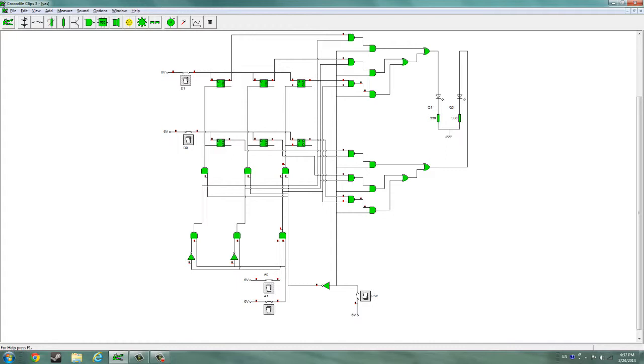Now, let's see how address leads work. There are 3 locations to save the data: location 1, 2, and 3. To save data in a specific location, you must represent 1, 2, and 3 in binary with the switches. A1 is the carry, and A0 is the first digit. So, 0, 1 is data location 1, 1, 0 is data location 2, and 1, 1 is data location 3. 0, 0 doesn't work in this case, since there is no memory cell associated with that input.